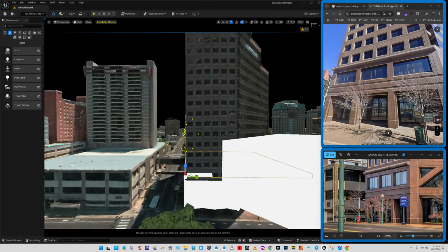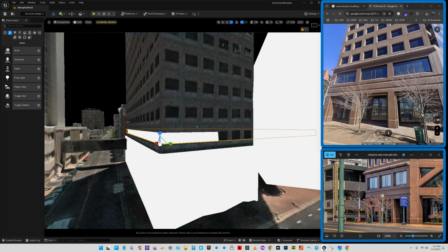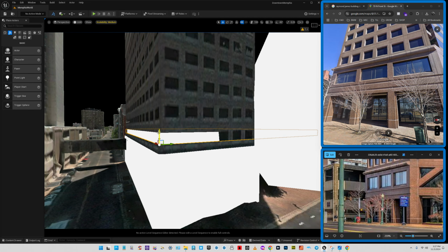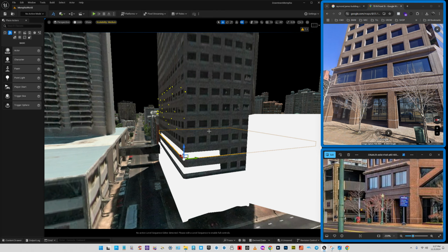let's go ahead and duplicate the Boolean. And we're gonna give it 2. We're gonna duplicate this with Alt and drag. Okay, and in SketchUp we can then do, let's go ahead and Control D and move these up.